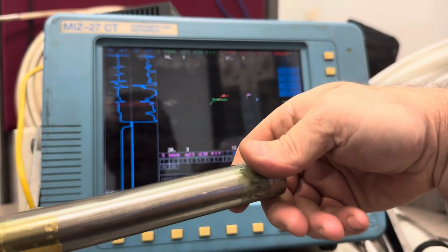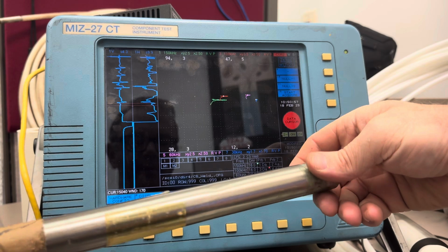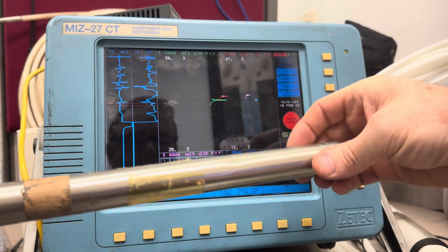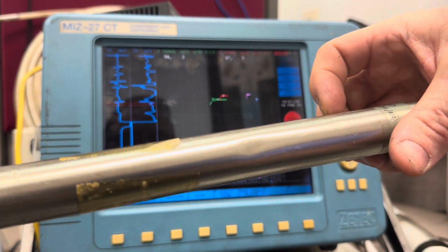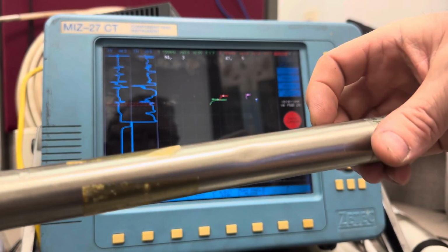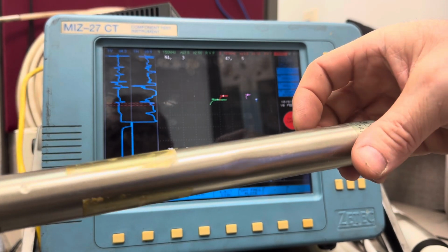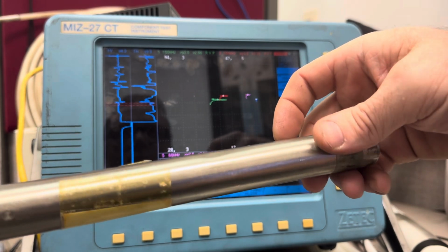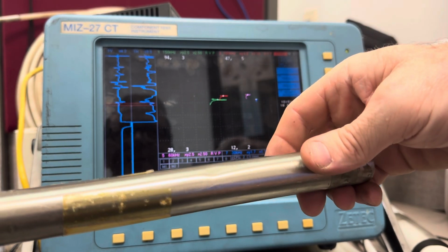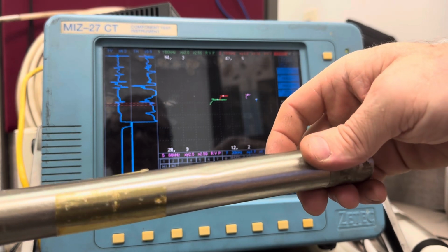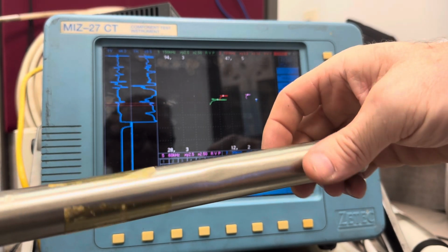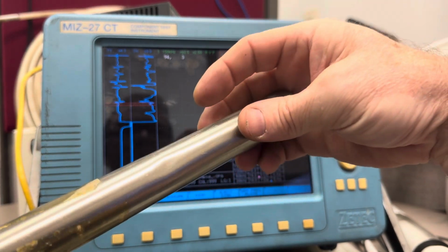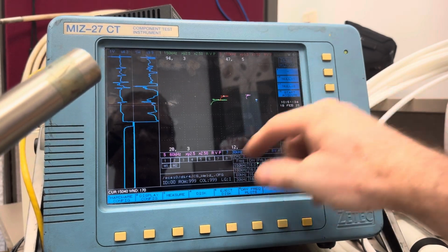Well, we haven't covered that yet in these videos, but I don't know if you can see it as I rotate this cal tube back and forth, but what do you see right there? That is a dent from the OD. Now, in your studies, you may come across some literature that asks, what type of signal, when you go 5 frequencies higher and 5 frequencies lower, doesn't really rotate much off the horizontal? And as you're going to see in a moment, that's going to be a dent or a reduction in tube diameter. So we'll see if I'm right.